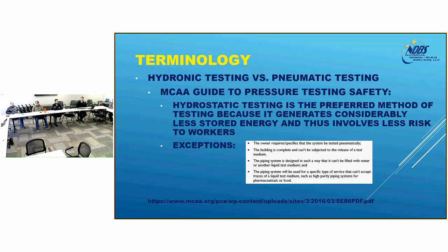But if you have an ultra pure system, like a water for injection system, they don't want you to put regular water in that system because it will create impurities in the system. And so ASME has ways around that too that don't even involve pneumatic testing, special system testing. So I gave a link to the website if you guys want to research that further.